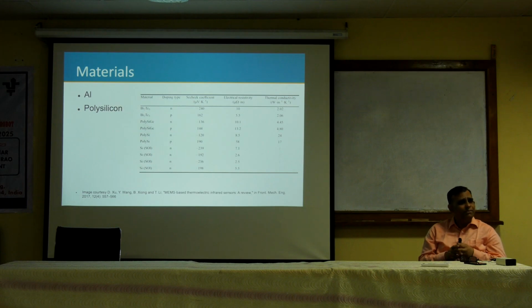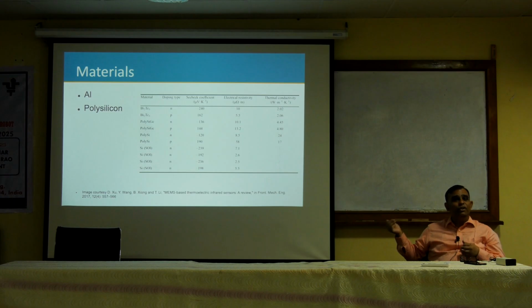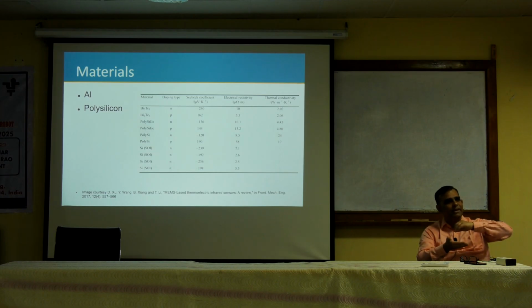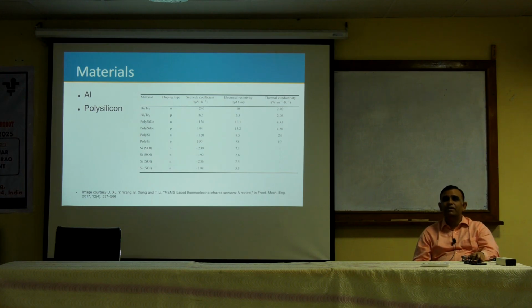And it's available. We made the transistor using polysilicon. So I don't need to introduce a new material in my process. Other things like bismuth telluride, which are on top, are not inherently available in a silicon process. Right? Even silicon on insulator means I have got an insulator base, then a dielectric, and then silicon. It's a costly process to make. So people used to make chips on things like silicon on sapphire or silicon on diamond. But polysilicon itself is available.